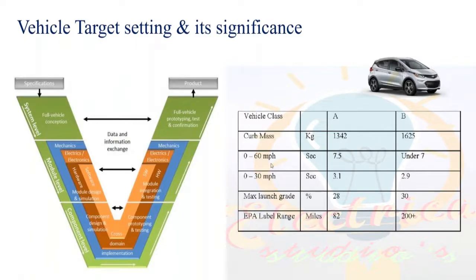When I need 0 to 100 km per hour in just 2 seconds, I have to develop the maximum torque. To develop maximum torque, I have to supply maximum current. But it is not just about supplying maximum current. The motor and the motor components, the inverter and the inverter components, should be able to withstand that maximum current. That is very important: the ability of the motor components and inverter components to withstand such a huge amount of current for a short span of time. That is what we need for better acceleration in a car.